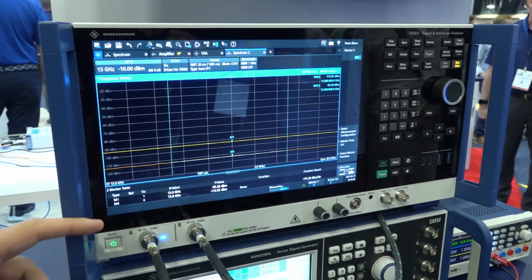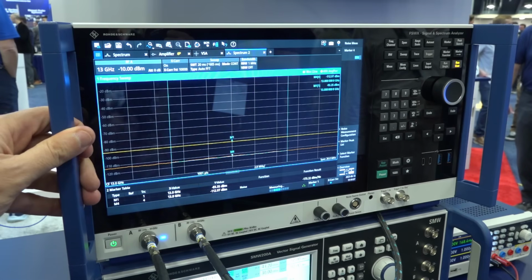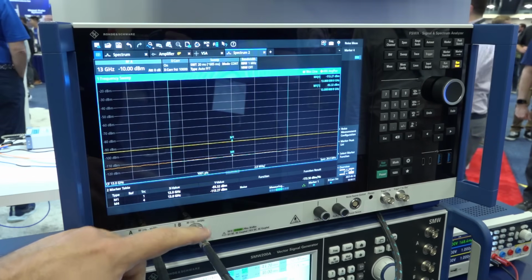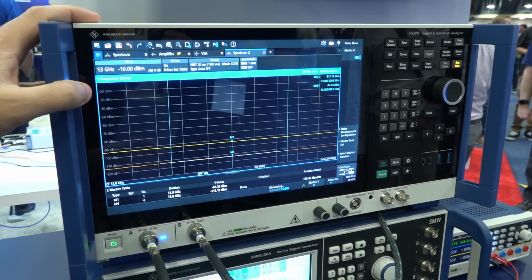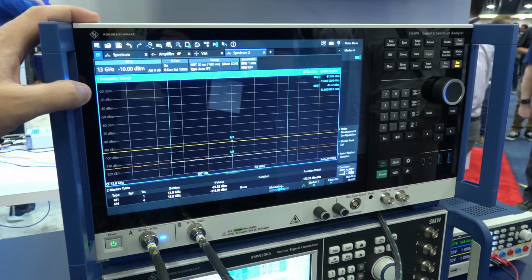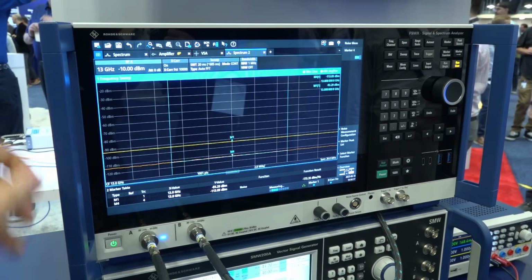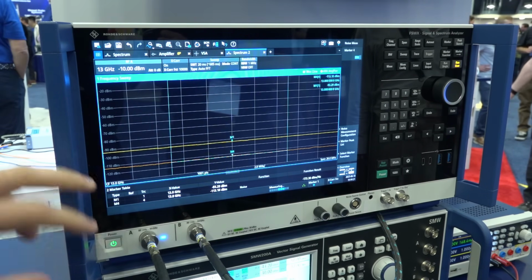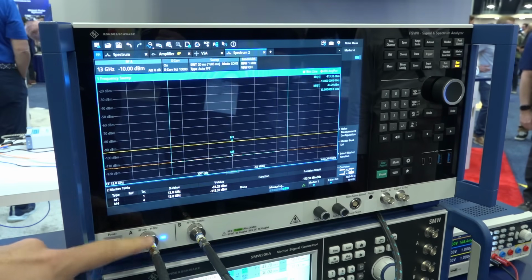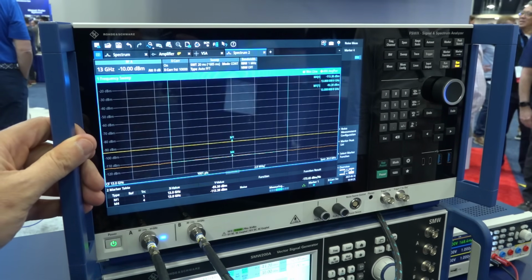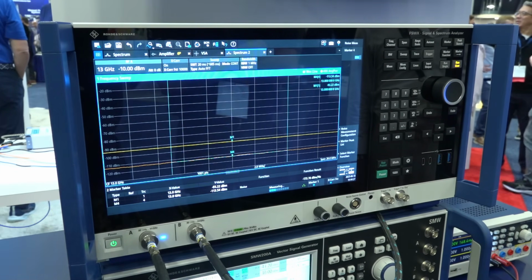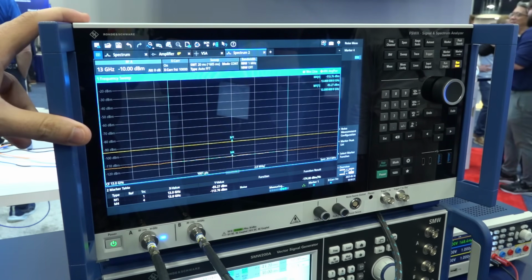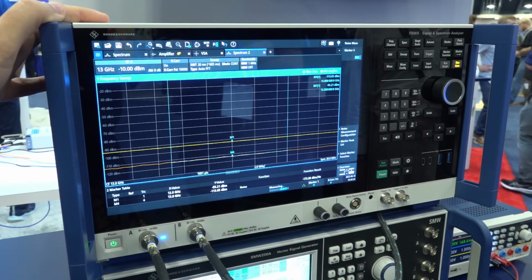This has a 2x4 gigahertz digitizer, so essentially the same 8 gigahertz complete digitization that you have from the FSW, but here now you can split it. Gives you a little bit of insight on how they do the digitization in the back end. But there's a couple of demos that I want to tell you about that they're doing here live. But the software capability of this and what you can do in the back end, having the similar body and sharing some of the LO must be quite fascinating. This is a completely different way of building FSWX and building spectrum analyzers in general, and it's going to be a big impact on this domain.